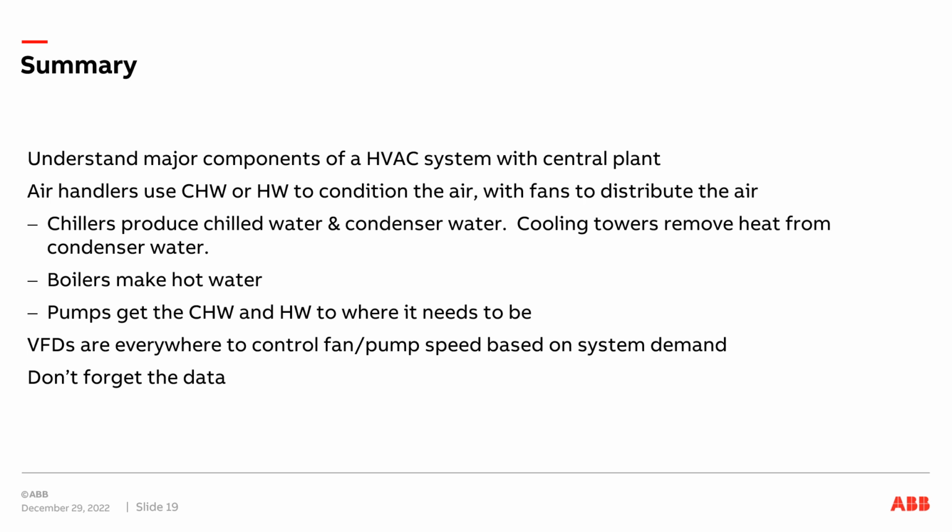And your pumps are going to have VFDs on to speed them up and slow them down based on system demand. And throughout all these graphics, there were little pieces of data there, whether we're looking at the trends, whether we're looking at how fast the VFD was running, just oodles and oodles of data is available in HVAC systems. So if you don't have that data, if you go after this presentation, you go look at your operator workstation, and you don't have that data, go ask your controls contractor, how do I get that data pulled onto here because I want to see it.